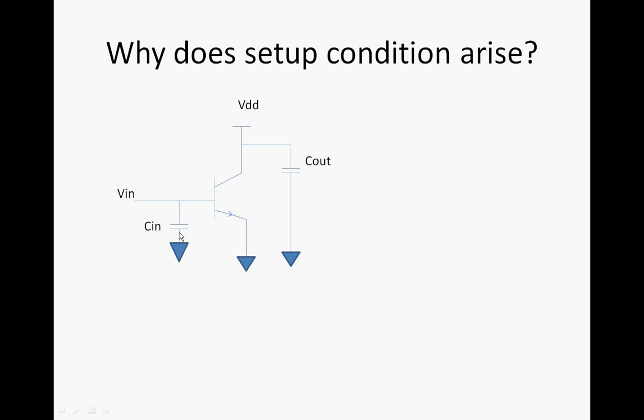Whatever voltage is present on this capacitor is what the transistor input sees. Similarly, when an output has to appear for the corresponding input, the transistor should operate in a mode according to the voltage input, like active, saturation or cutoff, and correspondingly it will charge its output terminal to provide the desired output voltage.